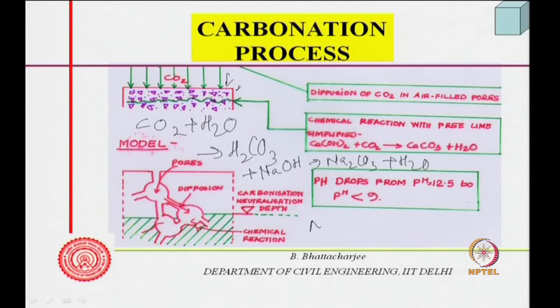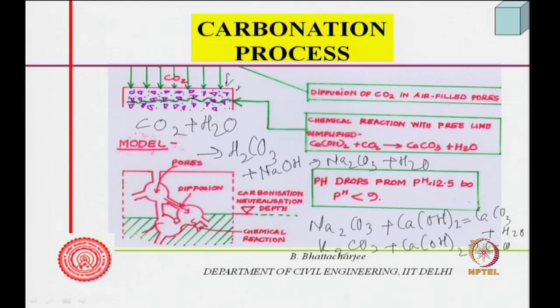Now, this sodium carbonate or potassium carbonate can react with calcium hydroxide in the cement, forming calcium carbonate and again water, and this also can form in this manner, it can form calcium carbonate and sodium hydroxide.